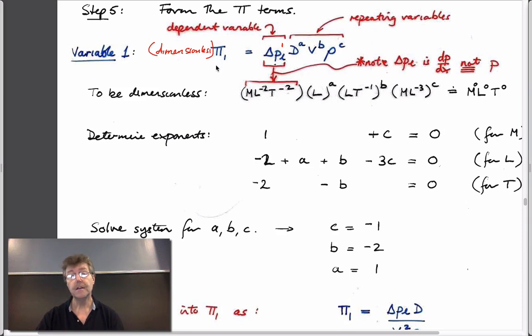That's basically it. You've noticed the Euler number and the Reynolds number that we use to characterize behaviors are non-dimensional parameters. So even though we're calling this subset of our class dimensional analysis, it's actually dimensionless variables we're looking for. And so we can work out the units of pressure divided by length: it's mass, length to the minus 1, time to the minus 2, divided by length. So that's where the second length term comes from.